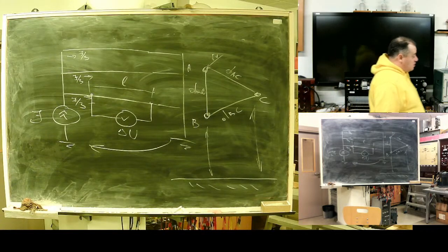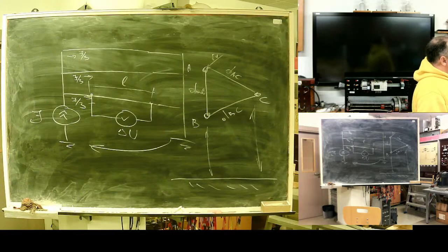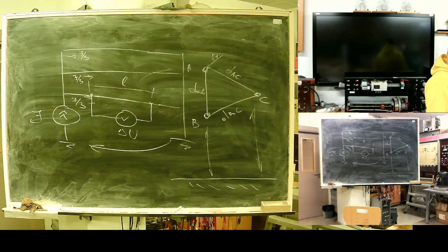It's quite common to assume that the line has a full cycle of transposition, assuming capacitance against ground symmetry. To transpose the line, we need to swap wires at a high voltage line to equalize capacitance against ground to prevent losses from this non-symmetry.